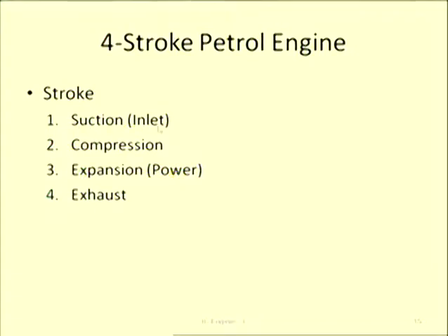Now how the suction inlet will happen, and how the exhaust will happen, depends on the valves. When we want suction, the inlet valve should open, and the air fuel mixture should get in. Now I want to do compression. If I want to do compression, then my suction valve should be in off condition. So in the suction stroke, the inlet valve is open, and the air fuel mixture or air will get into the cylinder, then it will stop. When the piston moves from top dead center to bottom dead center, it will create some vacuum, the inlet valve is open, so the air and fuel mixture will get in, or air will get in case of a diesel engine. Then the valve will be in off condition. So the first stroke is over, that is suction.